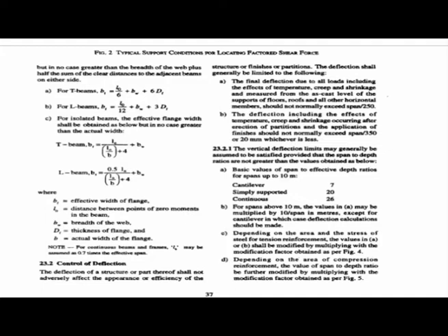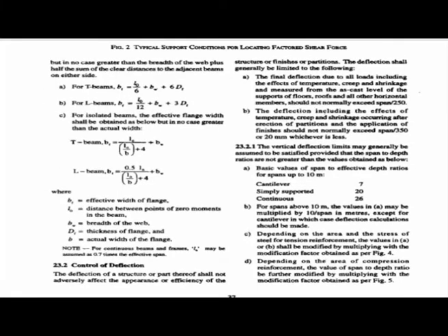So, this is the first thing, this is very, very important: that span by depth ratio. Later on you will find out that this will help you to find out the value of your deflection criteria also. Just quickly I am going through the relevant portion of the code.